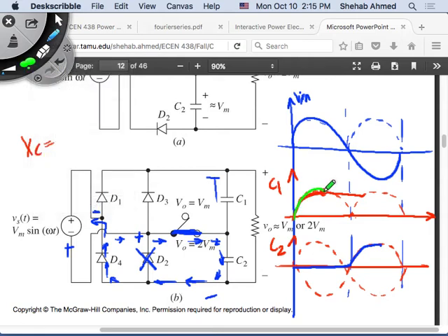What about the C and the loop? What do you mean? There is a voltage. So as soon as you start, okay, this is a resistive load, right? This capacitor has a voltage across it, even in the positive half cycle, right? And in the negative half cycle, it also has a voltage across. How about this? In the positive half cycle, it was 0, right? So current can still flow. What's the voltage across this? It's this voltage plus this voltage. So current will flow this way.